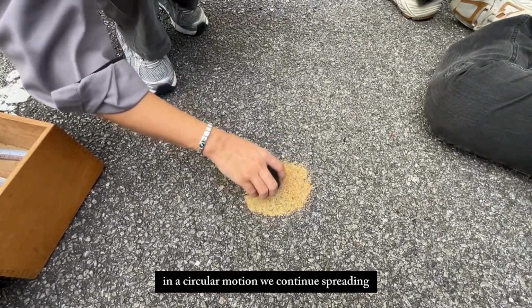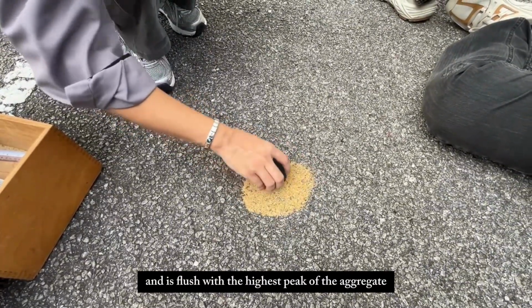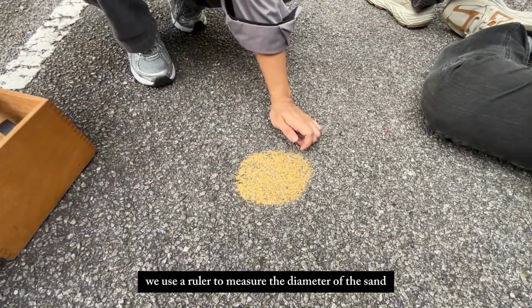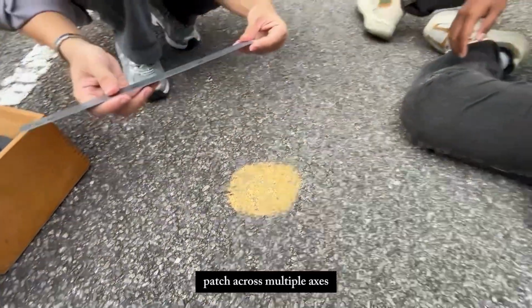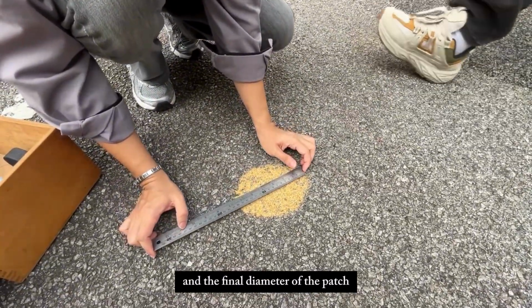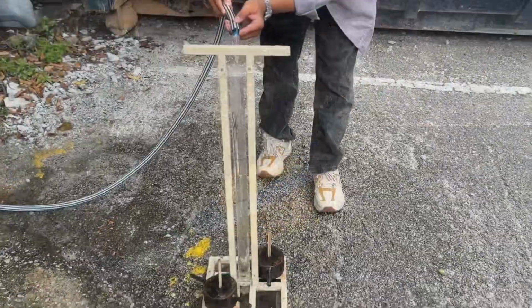We continue spreading until the sand fills the surface voids and is flush with the highest peak of the aggregate. Finally, we use a ruler to measure the diameter of the sand patch across multiple axes. By knowing the initial volume of the sand and the final diameter of the patch, we can calculate the average surface texture depth.